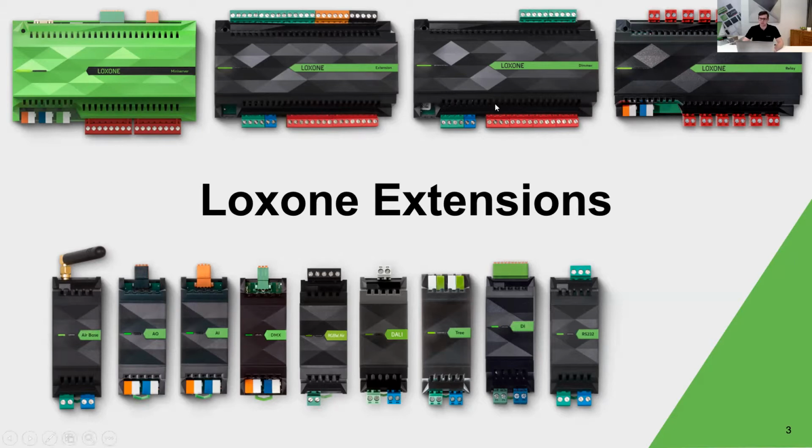And then at the bottom, these red terminals, these are your mains dimmed circuits. So a dimmer extension gives you 4 channels, otherwise known as 4 circuits of mains dimming. So you've got live and neutral in, neutral and live out on each of these blocks. So 1, 2, 3, 4.